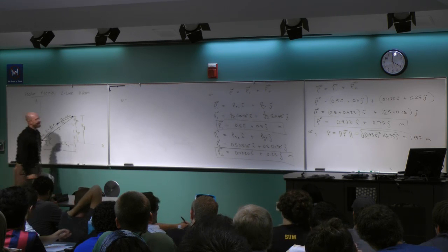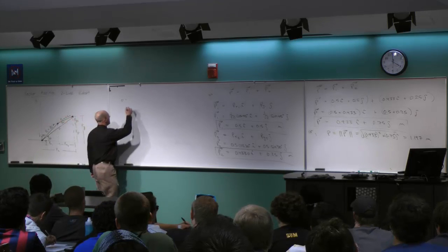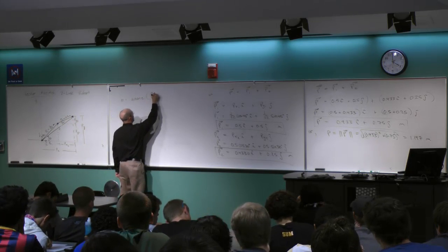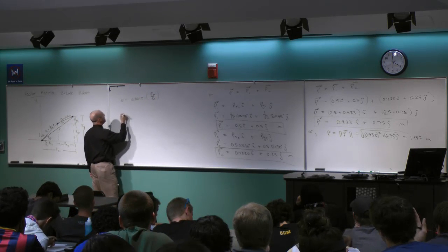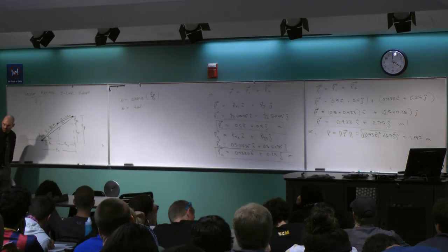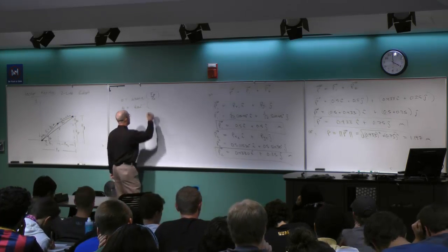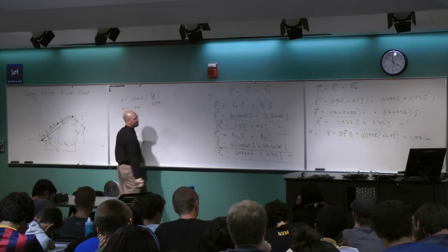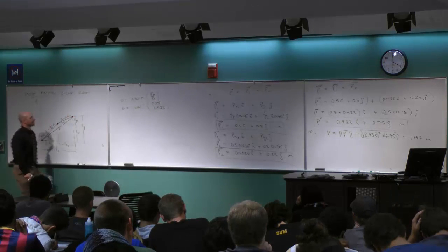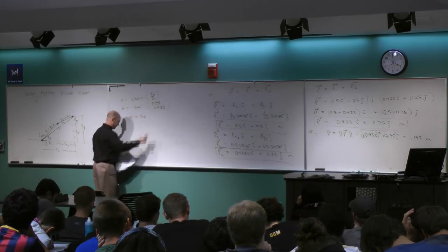looking for. Okay, so you want to keep in mind that whenever we do an inverse tangent on a vector, we're always thinking this. It's an atan2, right, of py divided by px. So in this case, this is the same as tan minus 1 because I'm in the first quadrant. So it's tan minus 1 of the y component, 0.75, divided by the x component, 0.933. Somebody run that guy. 38.79.